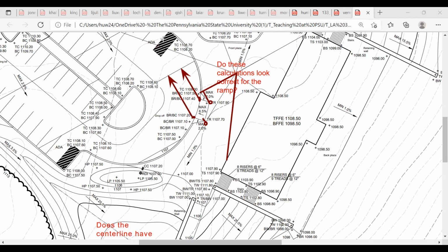And then BC is determined by the parking lot. Same thing. This spot, the BC is determined by the parking lot. All right. Using that one to calculate maximum slope. And I don't think the flare, the side of the slope, is calculated correctly. That one should be 8-9%, while maximum should be 8.33. Does that sound good? Or kind of make sense?